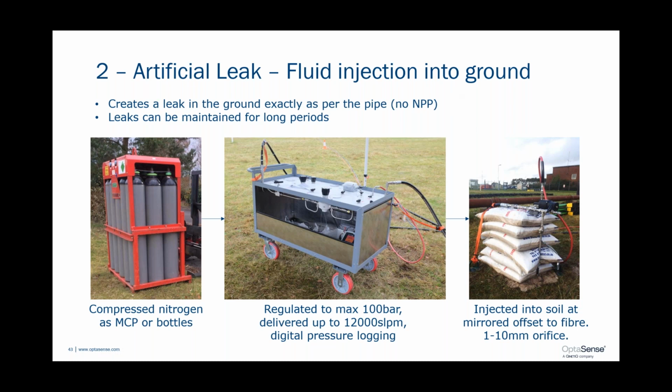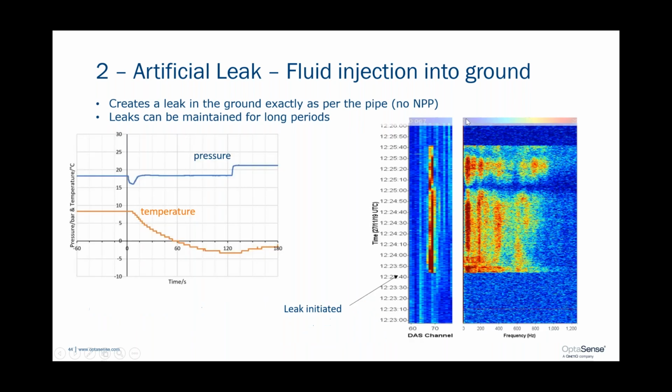And if we're matching our minimum specification and we're able to detect the modes that result, so the ground heave and the orifice noise, possibly some of the temperature change work, we've got a mechanism to verify the other three modes. So if we were to do the negative pressure pulse via a burst disc, we can do the other three modes via the fluid injection, gas at the moment, but we hope to follow with liquid quite soon. We now have a mobile field mechanism for verifying leaks.